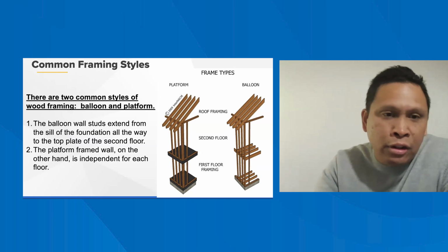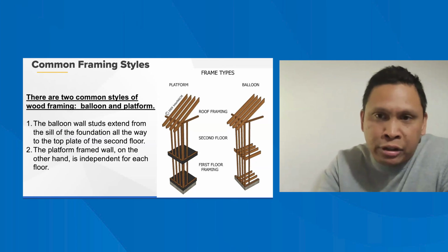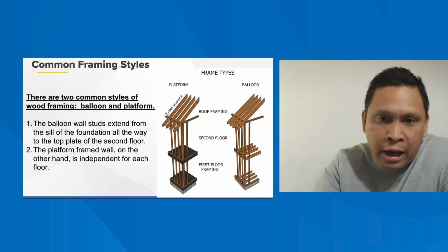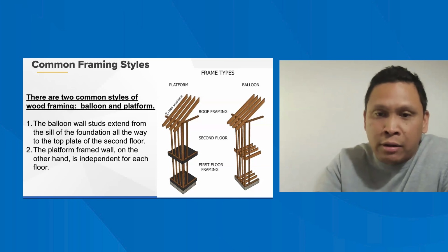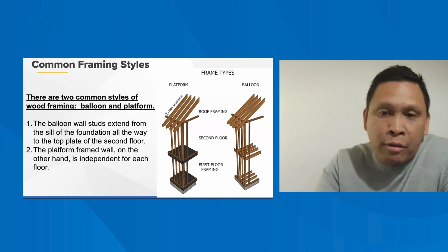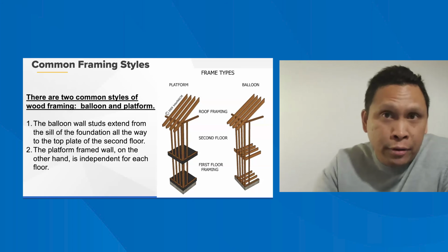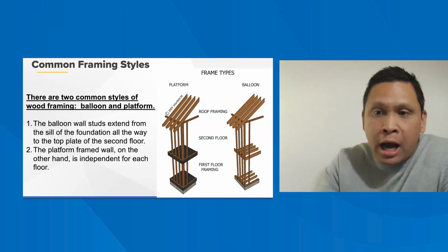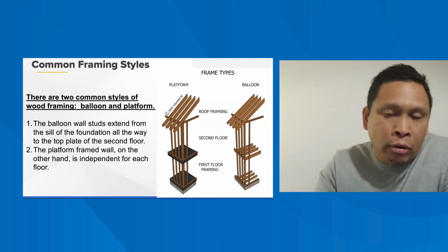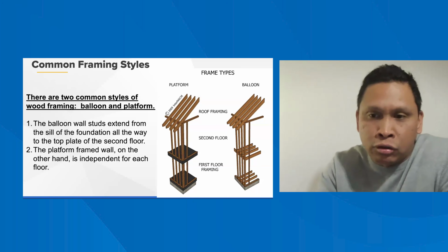Platform framing is the most common, as I was mentioning, that we're going to see today in home construction. It's made up of joists that help to support the walls, the beams, or the girders, and covered with either plywood, if it's an older home, or an OSB subfloor, oriented strand board.